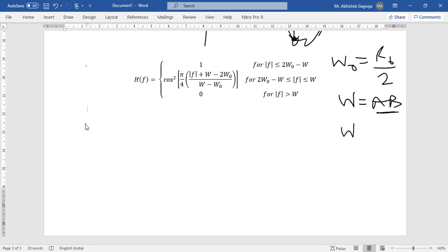That is, under any case, the transmitted bandwidth is not going to be greater than the bit rate, right? And that is a reasonable assumption. The transmitted wave cannot be larger than the bit rate. That doesn't make any sense. So the frequency of switching cannot be made larger than the switching you are already allowing. The bandwidth cannot be more than the bit rate.